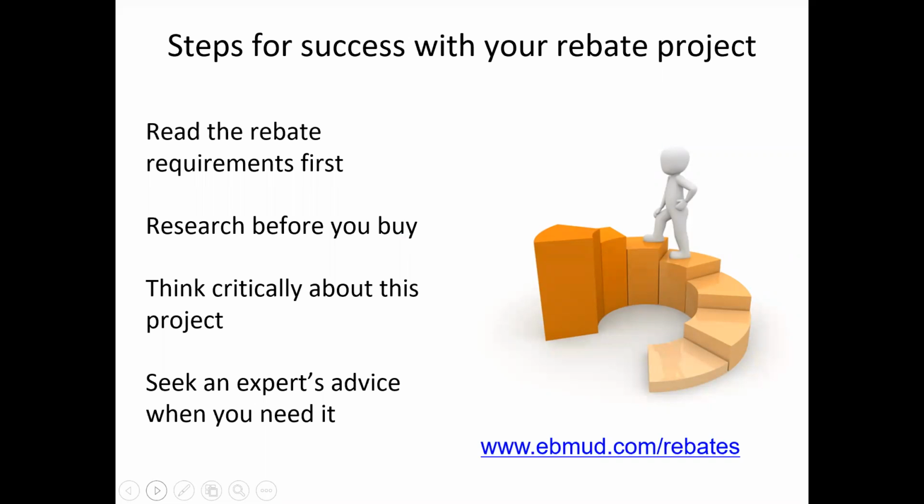But there are requirements and certain needs that we have. So I do recommend, before you go out and buy things and apply, read the rebate requirements first and research before you buy, and think critically about what your project needs are. For example, if you have high pressure on your entire irrigation system, does it make sense to just do the high efficiency sprinkler nozzles, or should you also be installing that brass pressure regulator?